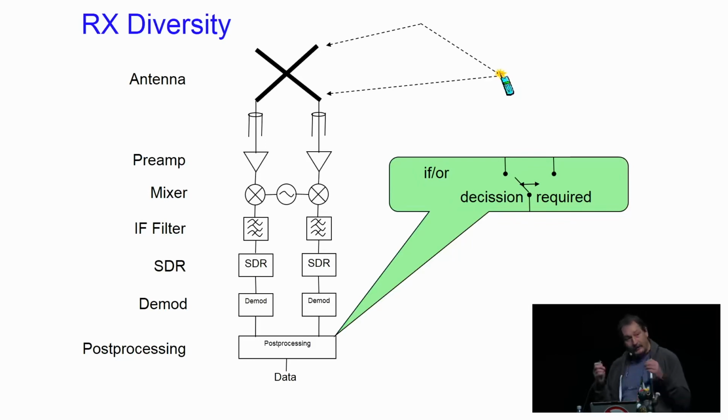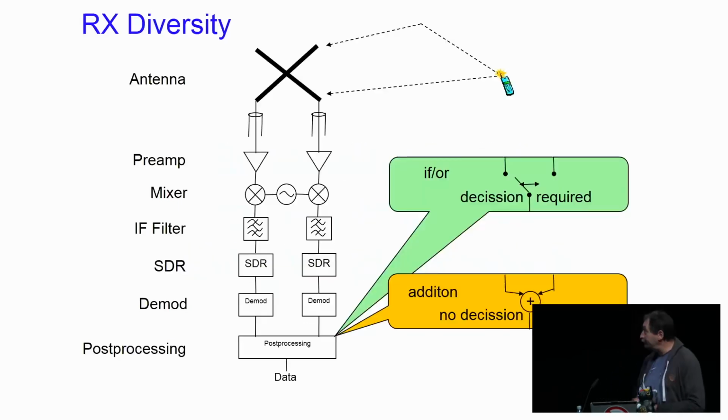And the advantage is if one of the paths has a high noise, for example, has some other interference, then I can switch it off. It has a high bit error rate, and I can see that, and I can switch to the other. But if I use only one, then the total reception sensitivity is lower.